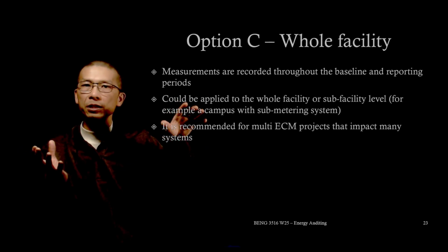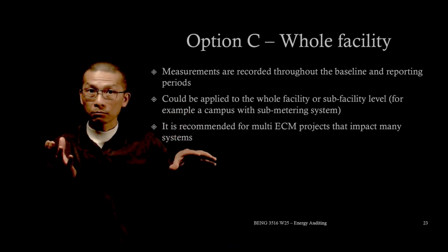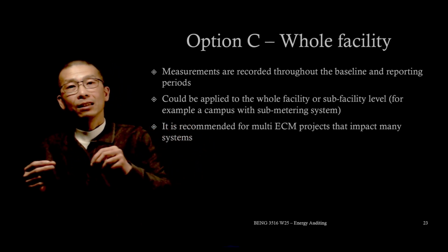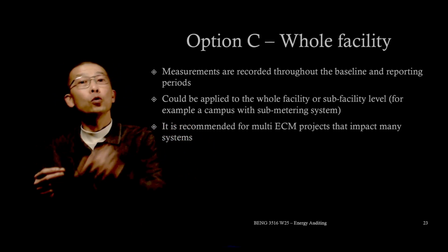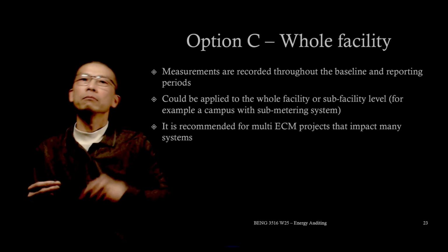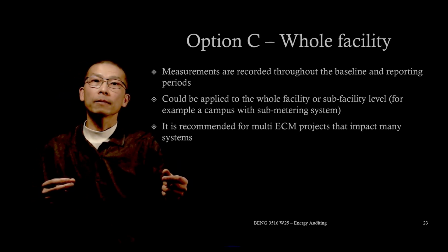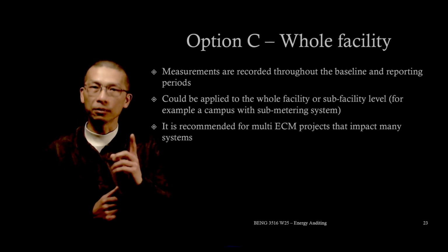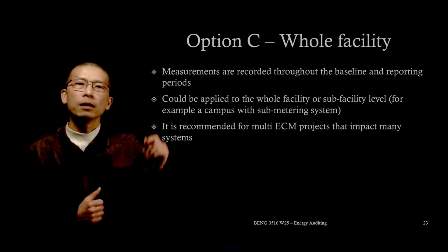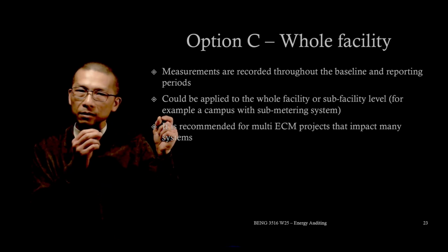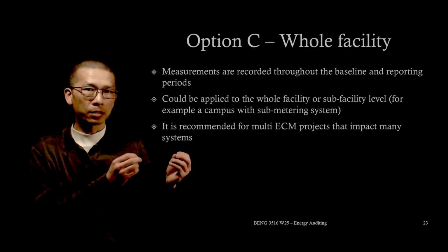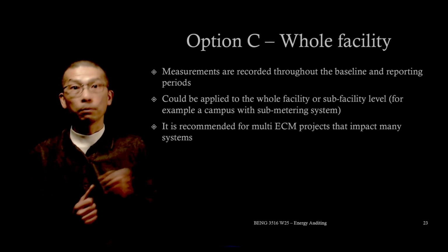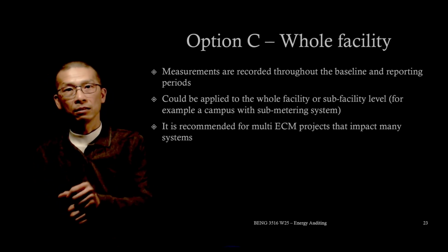And if we reduce the lighting energy use, it also changes the heating and cooling loads. Let me correct myself: the heat from lighting systems will increase the cooling load during the summertime, but reduce the heating load in wintertime.